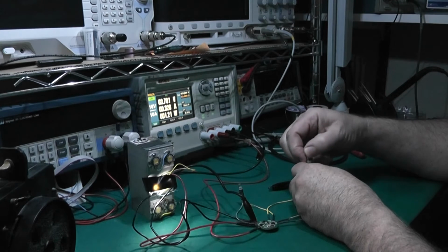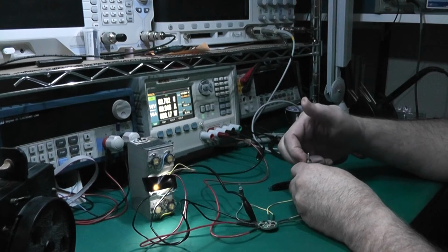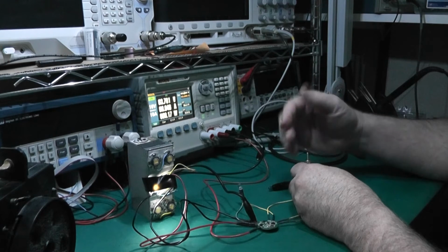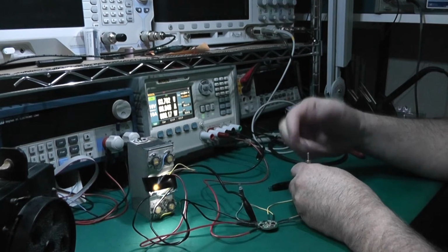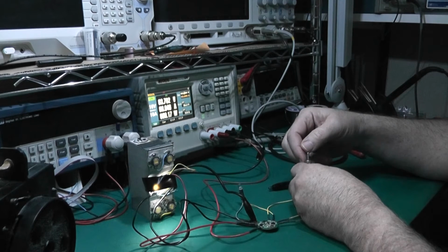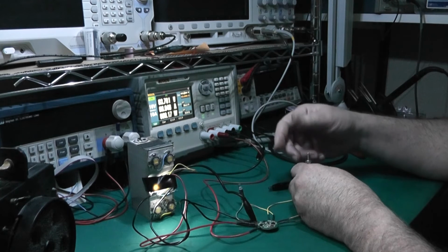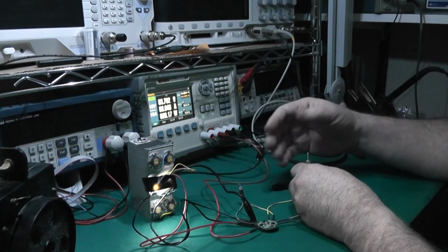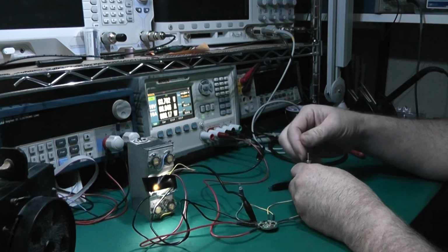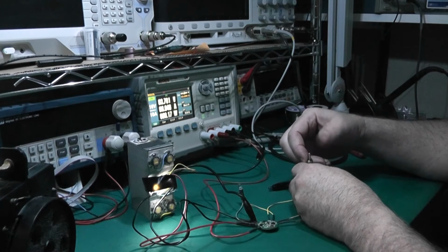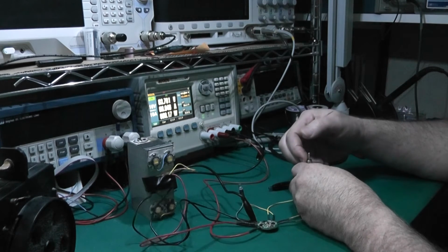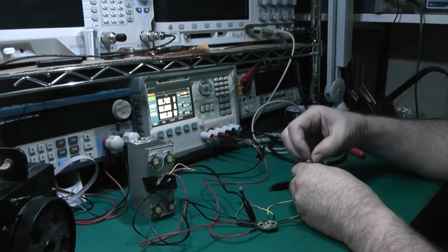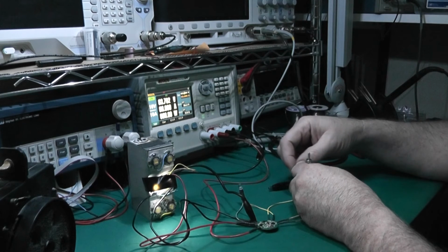So now to turn it off, we have to click down back to level 1. Now if we click quickly all the way down, nothing happens. We have to wait at least the guard band time, and that's configurable. Right now it's set to 0.7 of a second, and then you can do 2 double clicks, and those double clicks have to occur relatively quickly, but that's also configurable. By default it's 0.3 of a second. So if we do 2 quick clicks, click click, then the light turns off. And of course 1 click to bring it on.